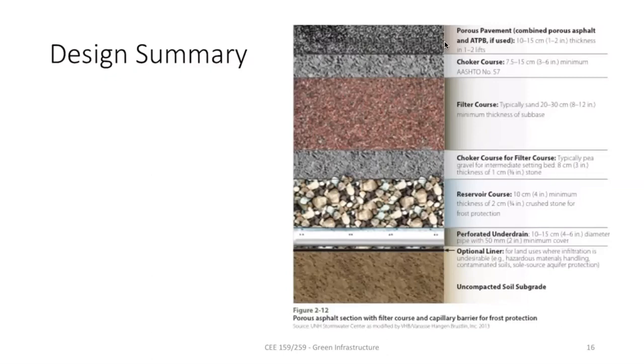But at the same time, if you don't have a bigger filter layer, you do have the reservoir course, or the storage layer. The difference between the filter and reservoir layer is the thickness and the size of the particles. In the reservoir course, the material is gravel or bigger. In the filter course, you have a sand layer, more like coarse sand.